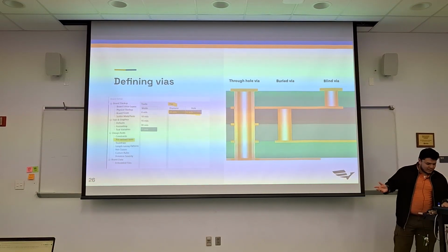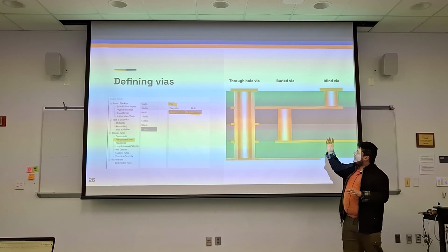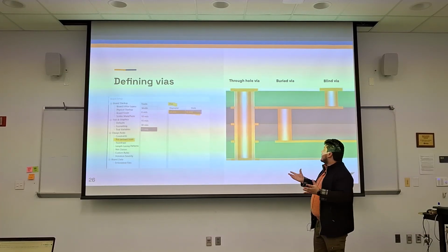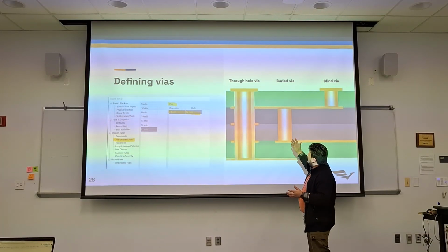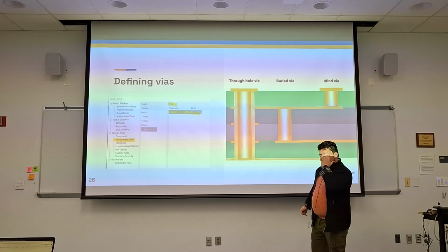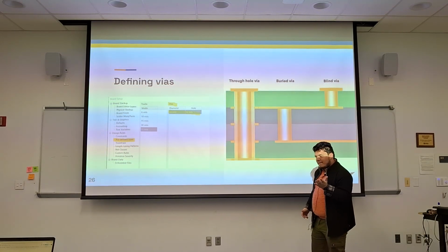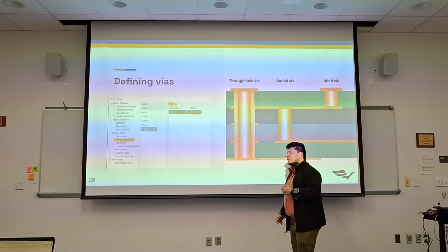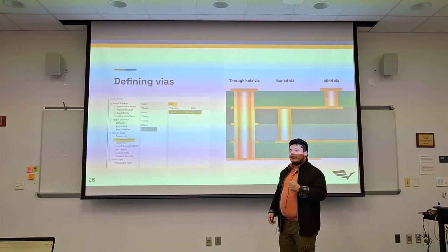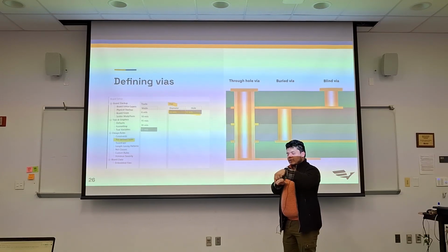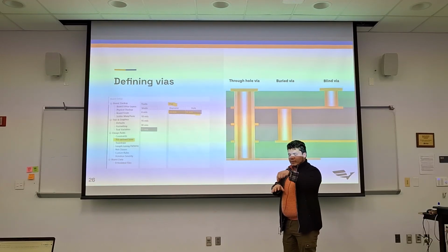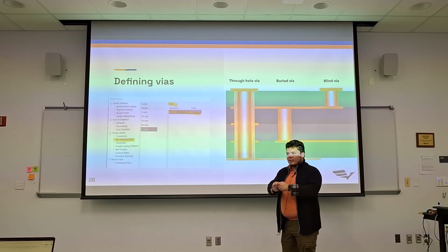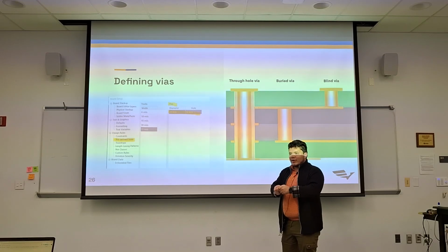And so this is where we get into the vias. As I mentioned, we have through-hole vias, which is what we're going to have on our design. Then there's also buried vias and blind vias. I mentioned them because they exist. And you will find this when you have a really, really high density of signals where putting a via all of a sudden cuts off your routing for a bunch of other signals. Because obviously it's a hole. So that hole is somewhere where you can't route a signal, right? And you also need clearance around the hole.